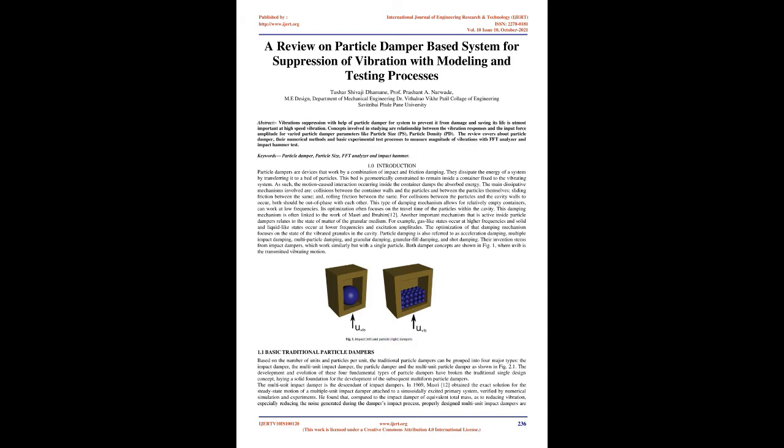For collisions between the particles and the cavity walls to occur, both should be out of phase with each other. This type of damping mechanism allows for relatively empty containers and can work at low frequencies. Its optimization often focuses on the travel time of the particles within the cavity. This damping mechanism is often linked to the work of Masri and Ibrahim [12].